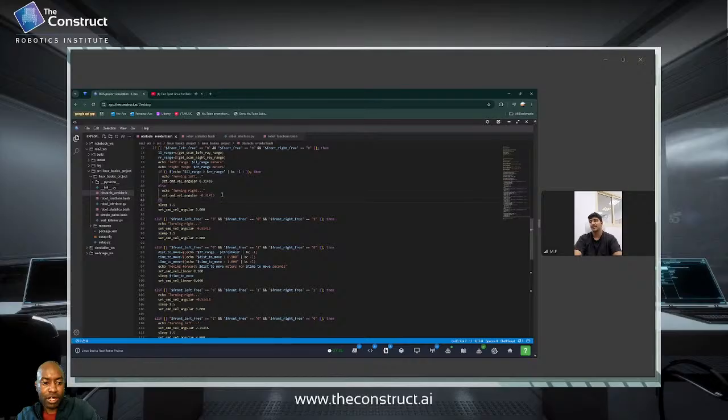When you tried 0.5, what made you change it to 1 and then to 1.5? That's what I'm trying to understand. When I did 0.5, it did turn, no doubt, but it wasn't a great enough turn to actually consider obstacle avoidance per se. It was more obstacle deterrence, just slightly turning away from it, not completely avoiding it. Then when I went to 1, it was just right, but there was always that possibility of it messing up. Eyeballing it just sort of made sense at the time.